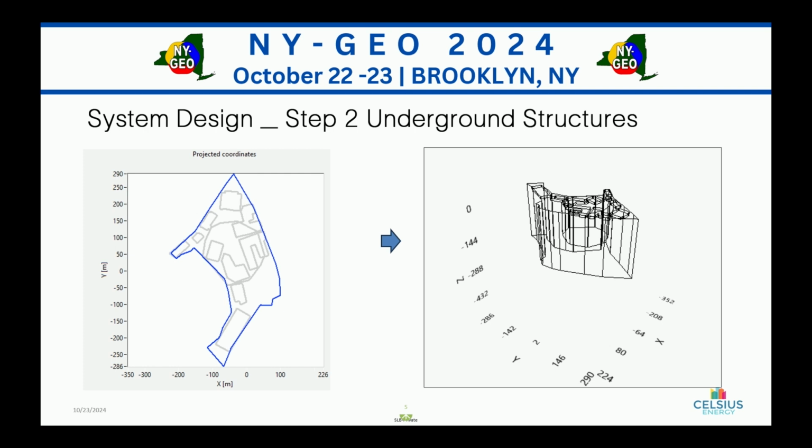Because we didn't have information about the direction and inclination of these bores, since no survey was done, we applied an ellipse of uncertainty to where we guess these bores can be. We apply a worst case scenario and assume at least 40% deviation. So we apply a 250 foot radius around this field to account for the possible position of the bore field. Then we space it out up to 500 foot depth and create a 3D model with the property boundaries, buildings, and the existing geofield.